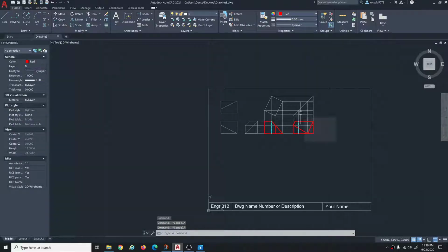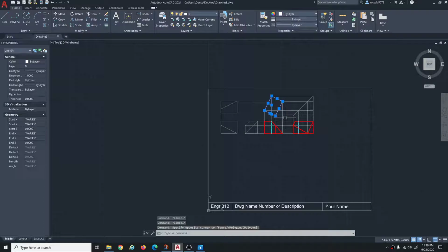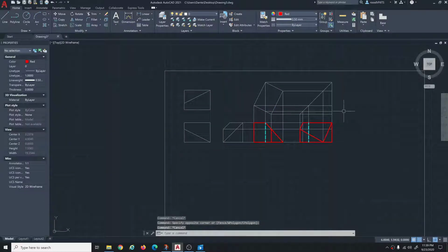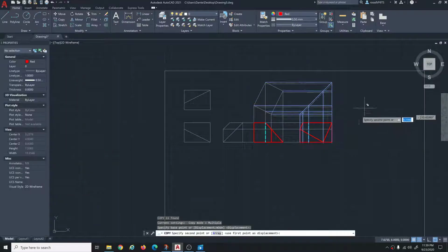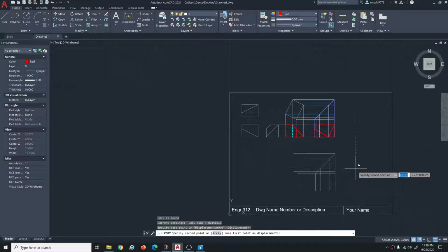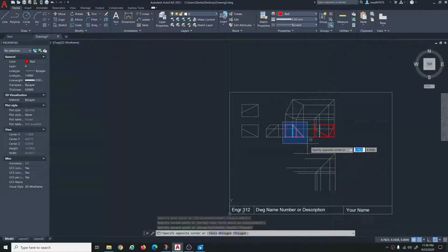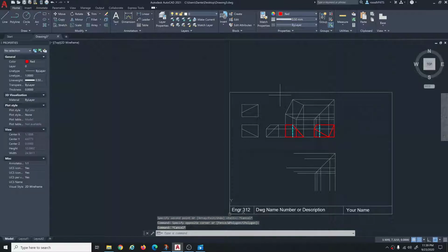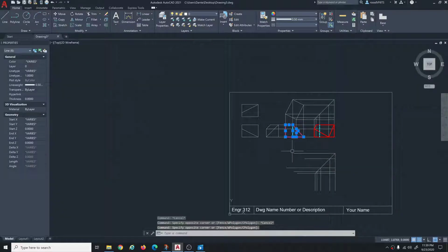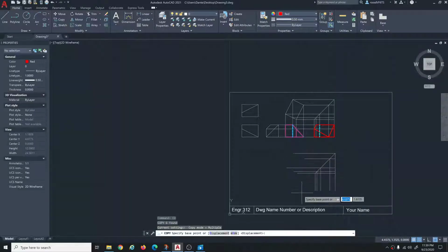All right, that was the first rotation. We took the top view and we turned it up like thus. All right, now what we're going to do is take these projection lines right here, all of those, and copy them down somewhere, like there is good. Then take the front view from the first rotation. So this up here is all the first rotation. We'll take the front view from that and copy it and put it right here.